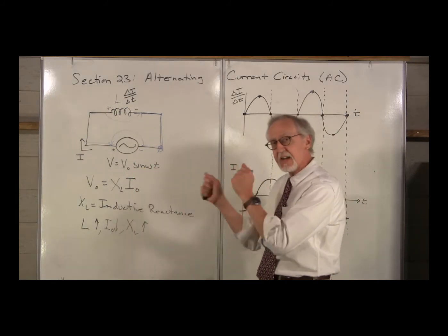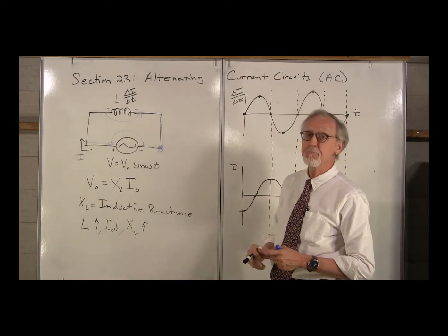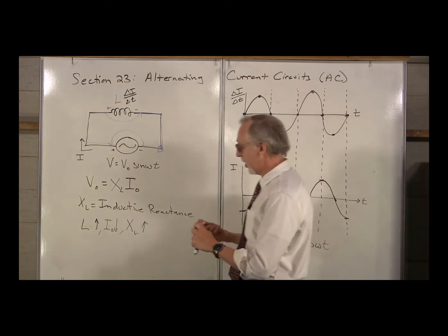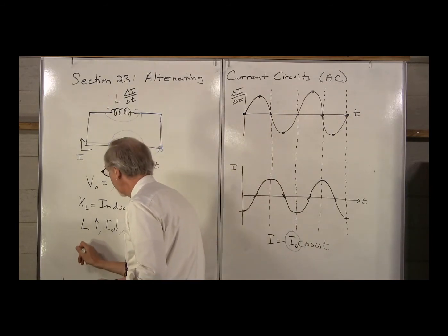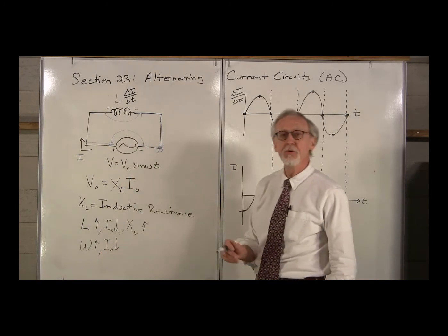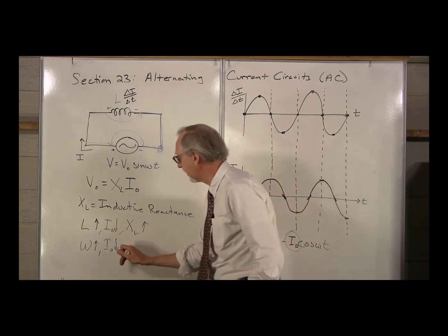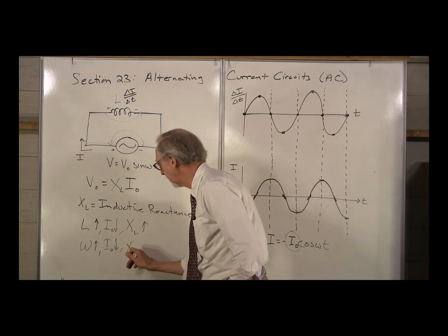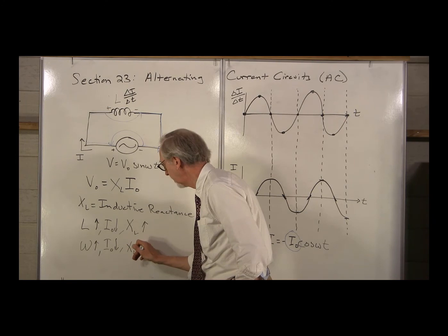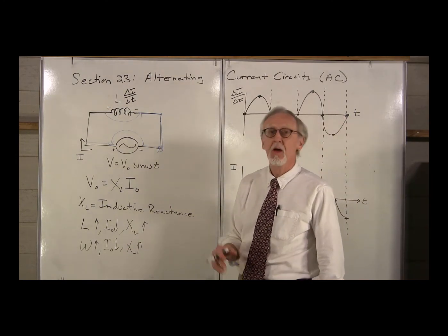If I'm trying to slosh it back and forth faster, the amount of current that's going to end up moving will be less. So, if we increase the frequency, the current amplitude must decrease. Again, if the current amplitude decreases, that must mean the inductive reactance must increase.